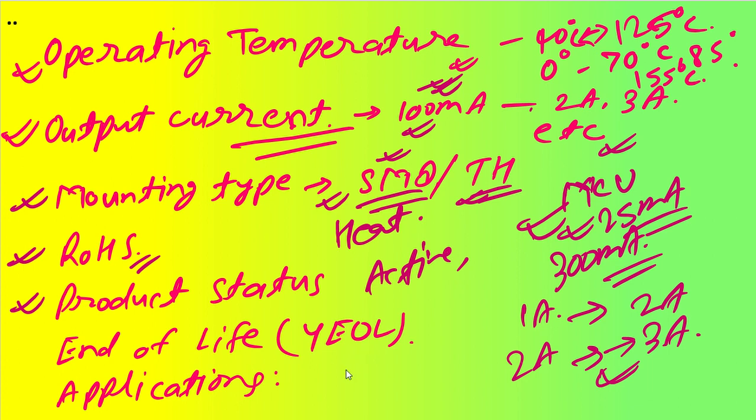So you can check this from the manufacturer website, or some of the third party websites like Silicon Expert and all. And many data sheets are actually giving the applications as well, like what are the different applications that the particular regulator can be used for. So this will help you to choose your regulators, right? Generally, they mention whether it is going to be used in FPGA supply, or wearables, or smart applications, or something like that.